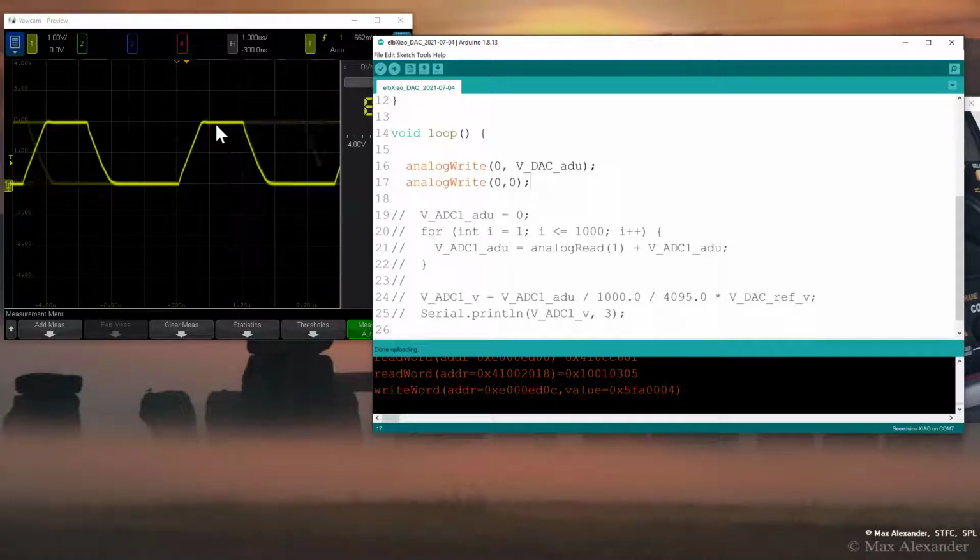We want to wait at least 2 microseconds so that we're sure we have a stable voltage on the output of the DAC. And likewise, the fall time. Again, it's about a microsecond, in this case at 2 volts. So given ourselves 2 microseconds to settle at the high side, 2 microseconds to settle at the low side, there'll be plenty of time going forward.